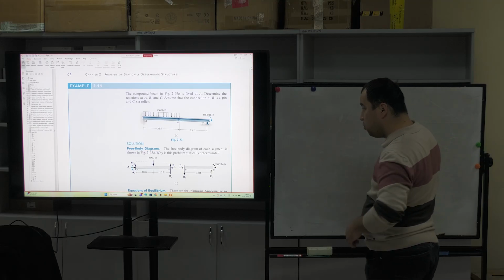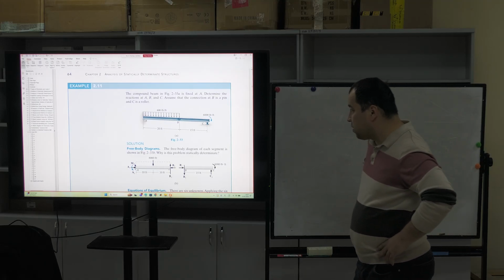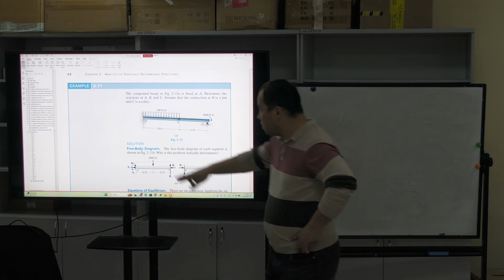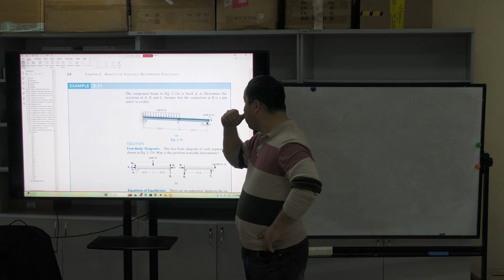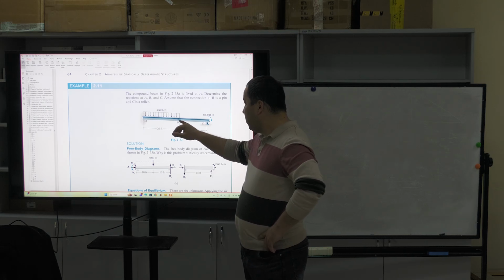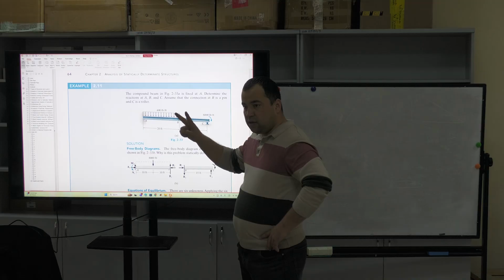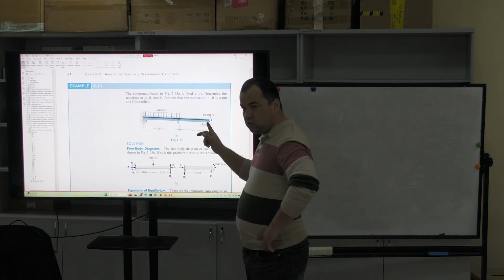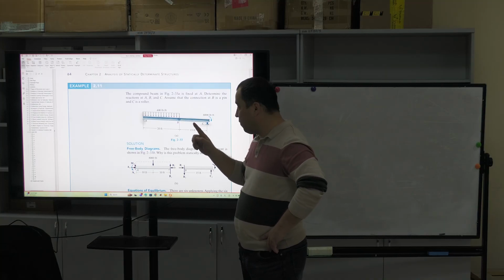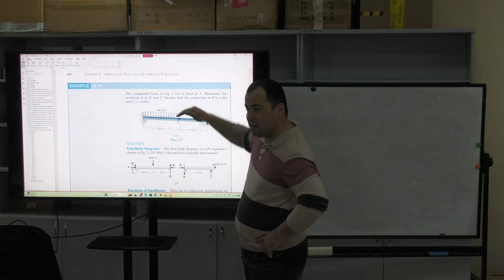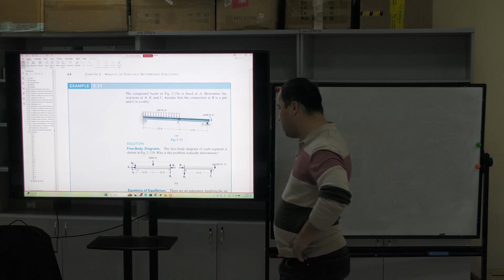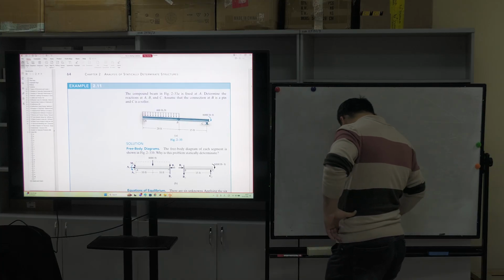Good. What we have here: 2 beams, yes? How many reaction forces exist? Just look. Point A is already fixed, and at point B, the internal hinge, both beams have 2 reaction forces. And this one is a roller support again, as in the previous one, with only one reaction force. If we rotated this one, it would be much more complicated. That's why the situation is also okay.